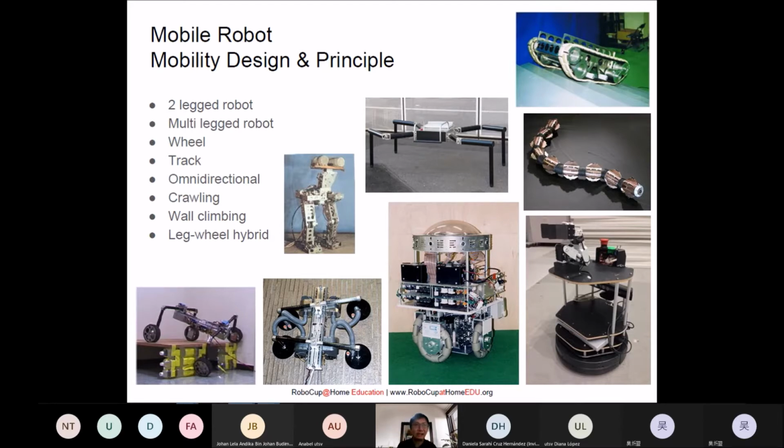So particularly in this class, we are using this very normal Roomba-style mobile platform that uses two wheels. Okay, and these two wheels are actually a bit different from a normal bicycle or the Ackermann steering in your passenger vehicle or car. Right, it's different. It is like two parallel wheels which move independently, left and right, which I will explain more in the next slide.